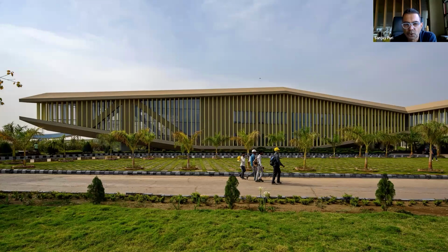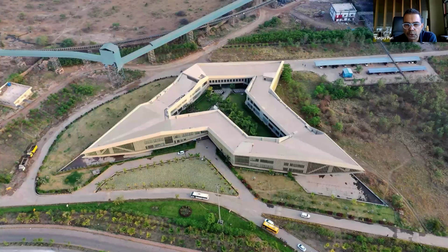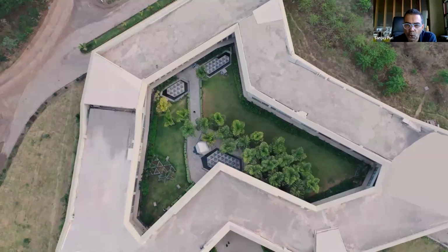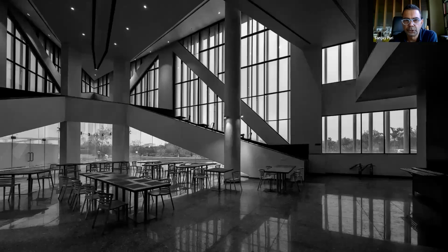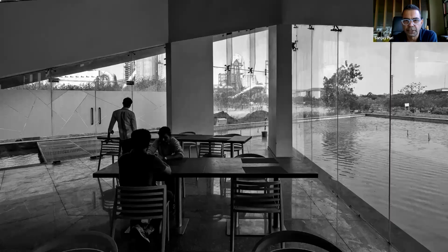And the vertical lines are all these metal aerofoil shaped louvers which direct the sunlight in. So you can face them towards the north and get indirect sunlight throughout the day. So that's the courtyard. You can see even now that there is a certain amount which is in shadow. So always, because the walls are closer, the courtyard is usable throughout the day. So this is the cafeteria space from the inside, opening up towards the water body on the outside.